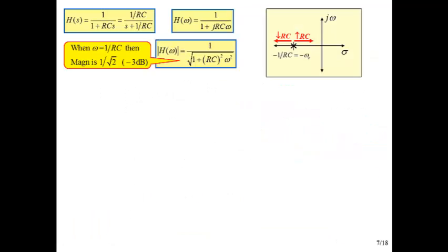So this just repeats up at the top the transfer function that we had, and since it is a stable system, we can replace S by j omega if we wish, and immediately get the frequency response, and that's the frequency response that we've gotten before. And you'll notice there that now I've gone back from that standard form. I didn't necessarily have to, but sometimes it's more convenient to write the frequency response outside of that standard polynomial form that we would get from S.